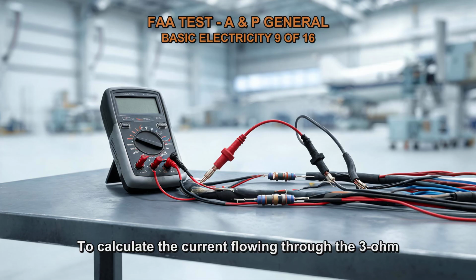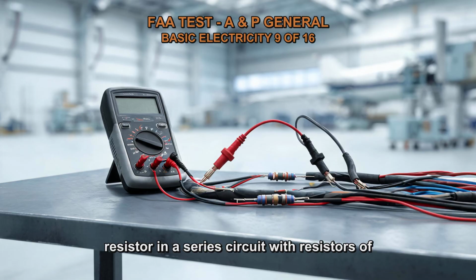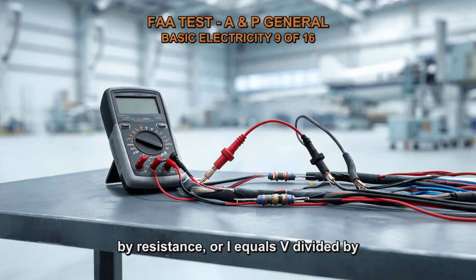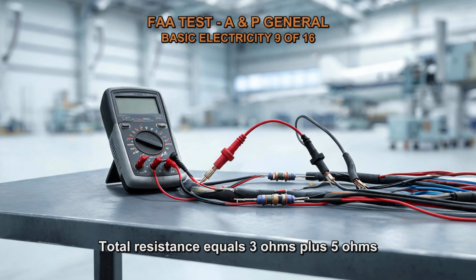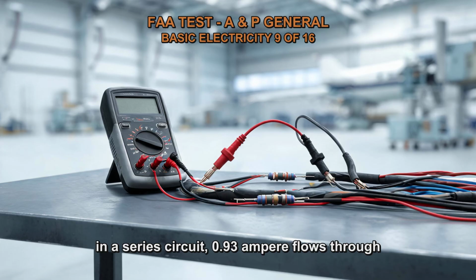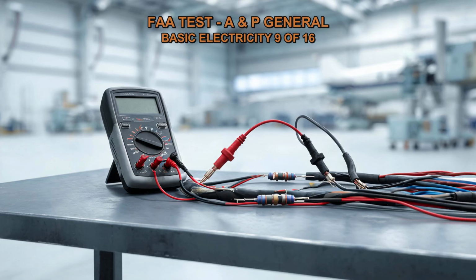To calculate the current flowing through the 3-ohm resistor in a series circuit with resistors of 3 ohms, 5 ohms, and 22 ohms, use Ohm's law. Ohm's law states that current equals voltage divided by resistance, or I equals V divided by R. Total resistance equals 3 ohms plus 5 ohms plus 22 ohms equals 30 ohms. Current I equals 28 volts divided by 30 ohms equals 0.93 ampere. Since current is the same through all components in a series circuit, 0.93 ampere flows through the 3-ohm resistor.